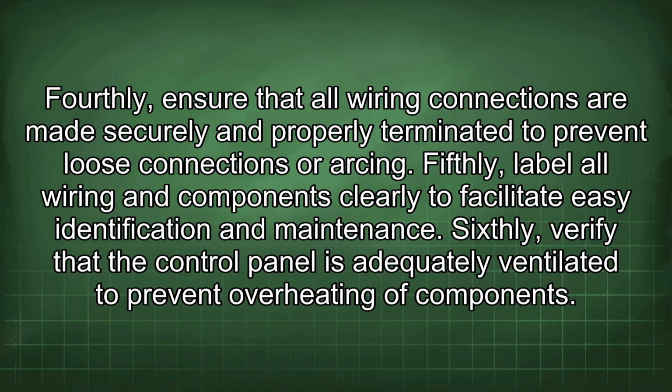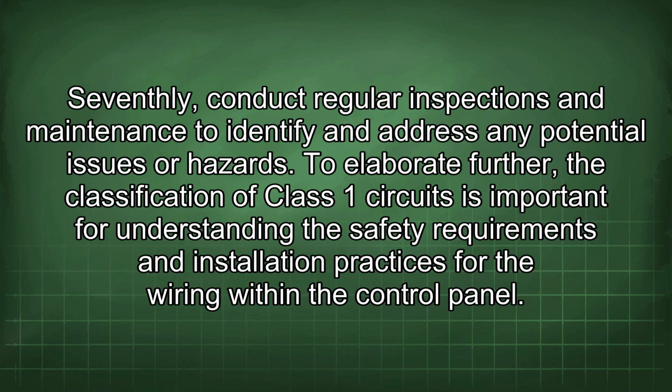Fifthly, label all wiring and components clearly to facilitate easy identification and maintenance. Sixthly, verify that the control panel is adequately ventilated to prevent overheating of components. Seventhly, conduct regular inspections and maintenance to identify and address any potential issues or hazards.